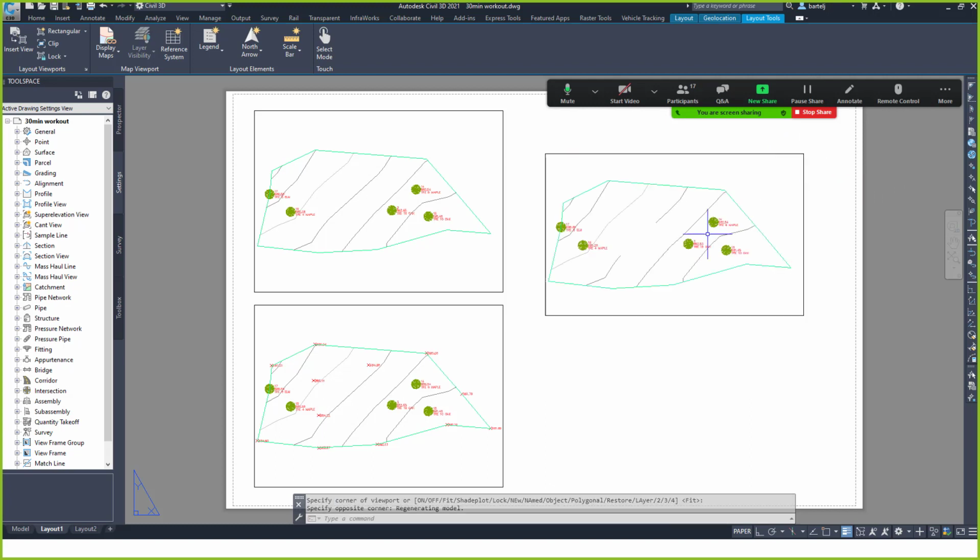And when I create that viewport, we can see that the information for those points or that V-node layer is frozen in any new ones. So as a mechanism, by creating additional viewports, you know what, I built this, but I never want this to show up in any additional viewports that I have. I can use the new VP freeze to be able to control that.